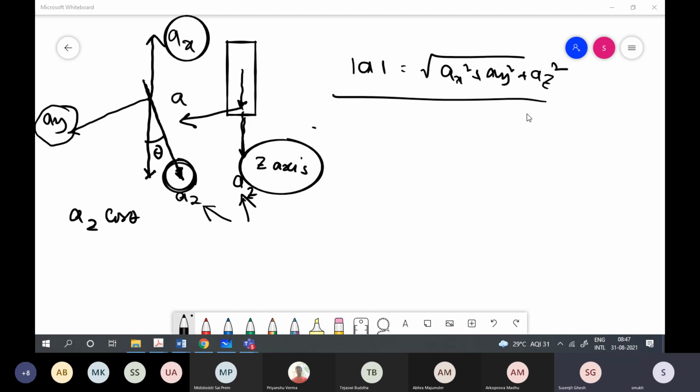Yes, sir. So the input is plus minus 3.6 G. You can see my screen, right? Yes, sir. Sensitivity is 300 millivolts per G. These are nominal. So this output comes to plus minus 1.08 volts over the range.